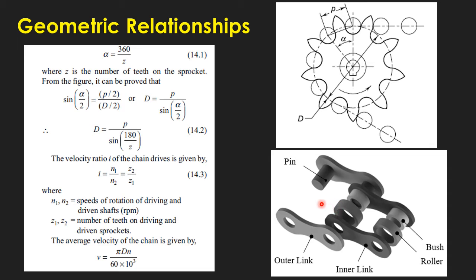I think I missed out one particular concept which needed to be explained. That is the concept related to pitch. I cannot go back to the previous figure. As I said, if wear is taking place in the chains, then the chain will get extended. When the chain gets extended, a parameter called the pitch of the chain also increases.